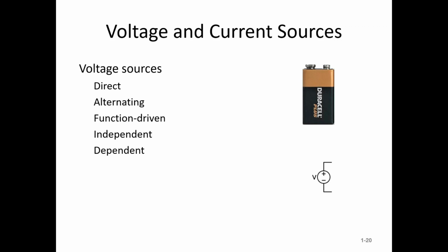So if the bus voltage starts to drop, there's a dependent current source in the alternator that will rise a little bit, and that will bring the bus voltage back. So once again, in the alternator there's a dependent current source, which would be a diamond in our little diagram, and it's putting out a current that's inversely proportional to the bus voltage.